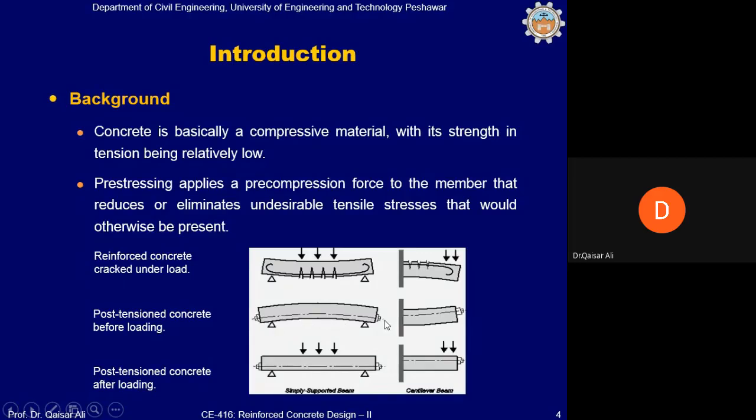And if then concrete is poured inside, the steel wire which is in stretched position will be enclosed by the concrete. And when concrete attains its full strength, then if the wire is cut on both sides, the wire, in its effort to regain its original length,